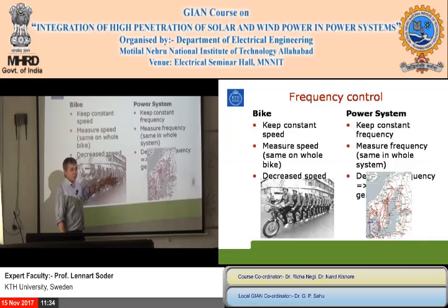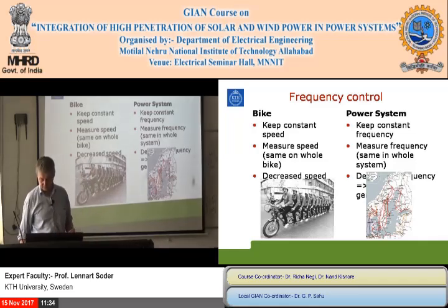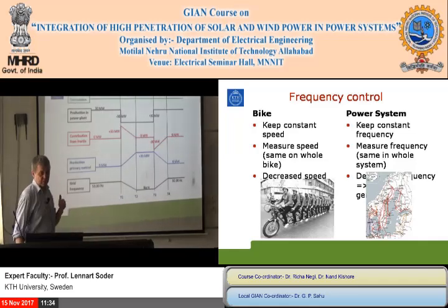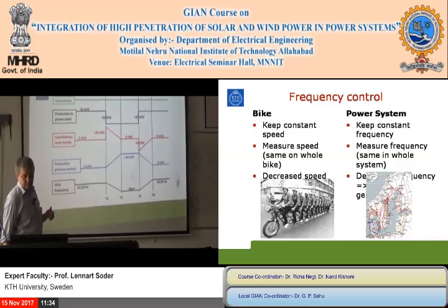It's 1.3 tons. On the other hand, assume that these were slim guys, weighing only 1 kilo each, and you have a plastic bike, and someone starts to brake. What happens? This is exactly the inertia problem you have in the power system: you need inertia, otherwise any changes will cause rapid changes in the frequency in the power system. So now back to this one. That is exactly what is happening in this one.